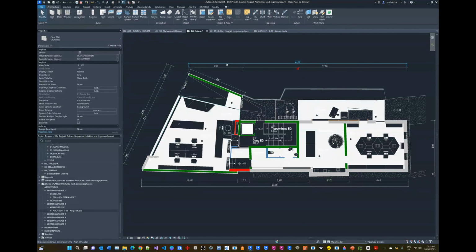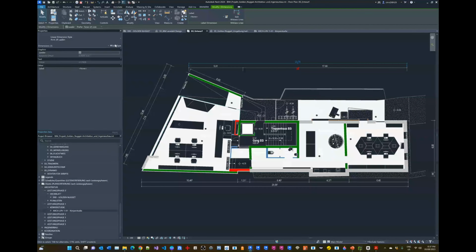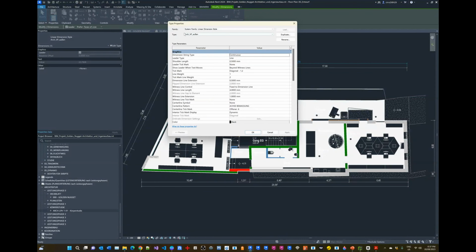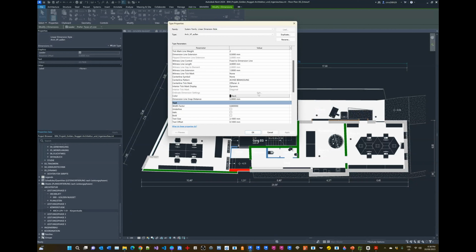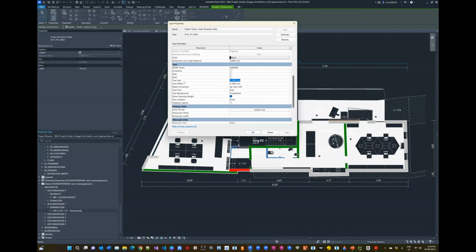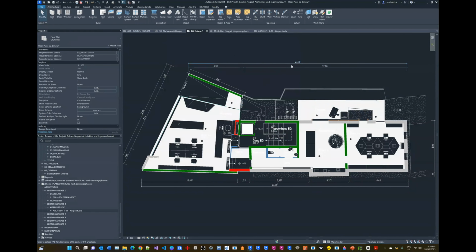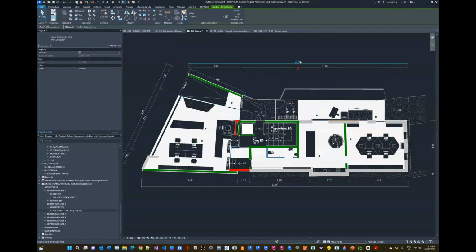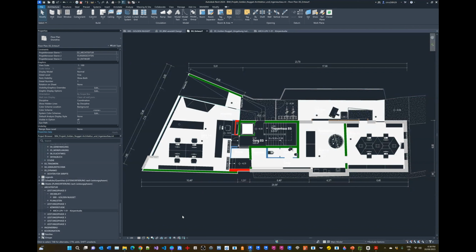What we do set up in Revit, however, is the size of the text that we want it to be on paper eventually. So if I look at the properties here for that dimension, I can see that I've got a whole lot of stuff here, but we've got things like the line weight there. Somewhere here will be the size of the text. So here we can see the text size is 2.1 millimeters. And there's a text offset, etc. So these properties will be the ultimate size of the text component once it's placed on a sheet based on the scale that we select here.